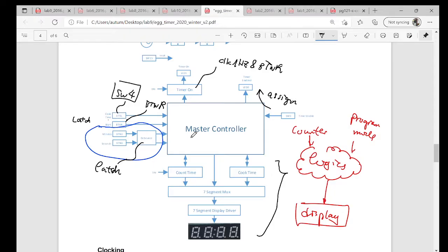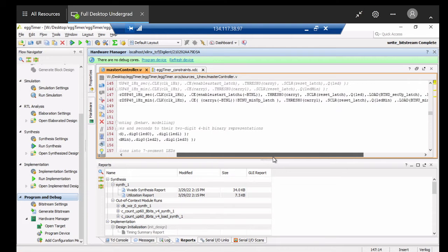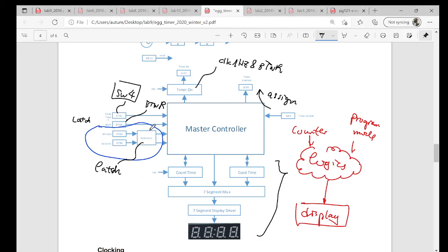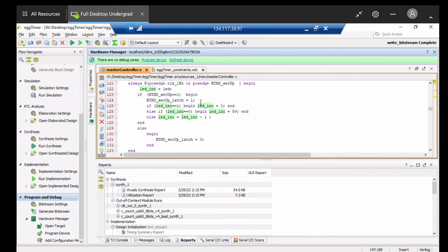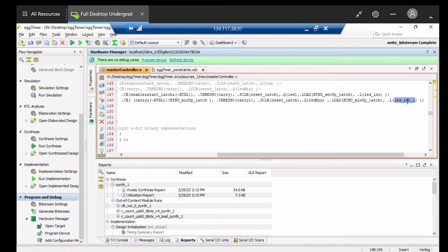Then after that, we should talk about the counter. I generate a counter with load and 8-bit output, which counts 60 times. For the load, I actually have to use a latch to make sure that it can cover 1 clock cycle, which is to avoid the bouncing here. I have also loaded the output from the debouncing circuit. These 2 are from above. After some calculation, I add it back to here to the load and load this new value to the counter.